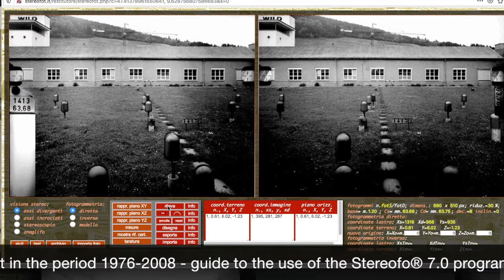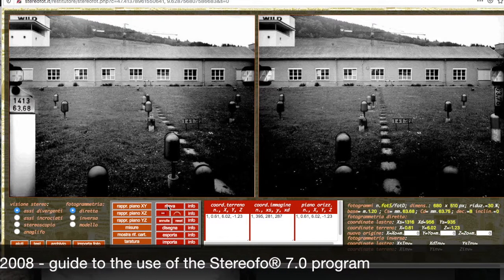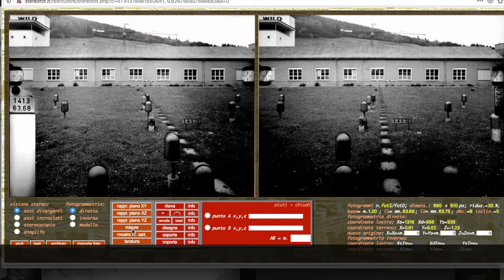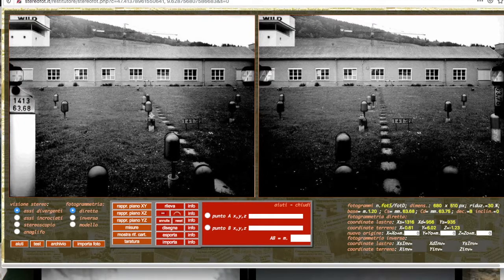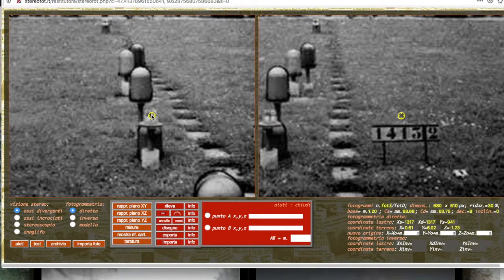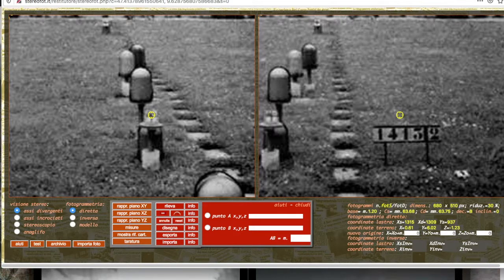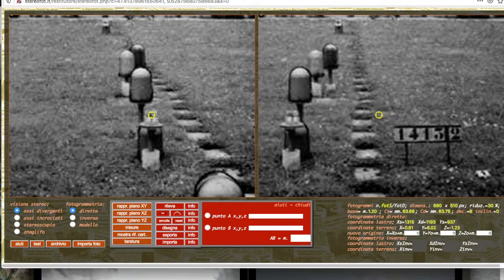In this case we have chosen the closest target, and we found only in the Y an error of 2 cm on 6 meters. To know the distance between 2 points, just click on the Measures button, and a new small window appears with 2 radio buttons A and B. The first point is detected and clicked on A. The second point is detected and clicked on B. The distance appears in the field at the bottom right.